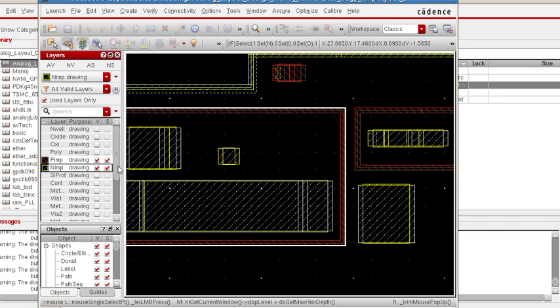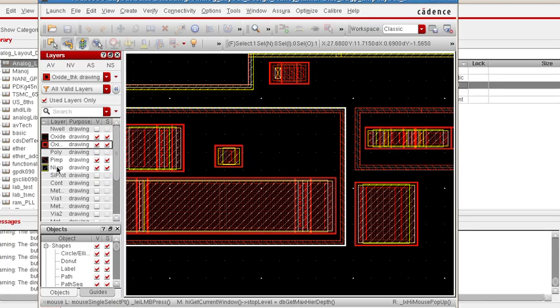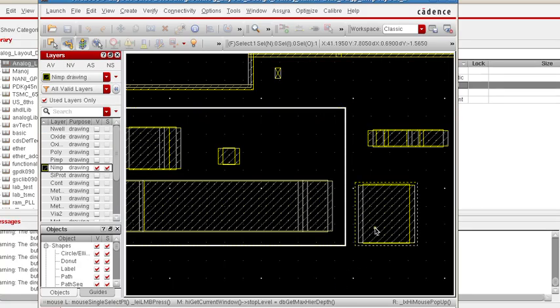So we can see under the OD layer, the oxide layer or thick oxide layer, we will have the diffusion layer. There is a possibility of electrical interference between those two diffusion layers under the OD. When the OD is shared, we will not have electrical interference, but when the OD is not shared, there is a possibility of electrical short or electrical connectivity between the two devices. Here we have the necessity of electrical isolation between the two different transistors or two devices.